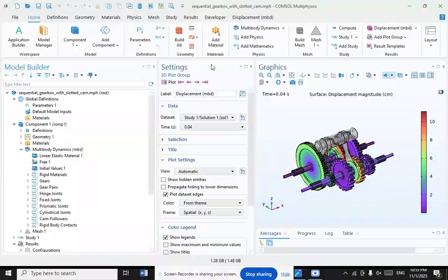The fixed and the free gears can be mounted on either the input or output shaft or both. For example, a 5-speed transmission might have the first to second selectors on the countershaft, but the third to fourth selector and the fifth selector on the main shaft. This means that when the vehicle is stopped and idling in neutral with the clutch engaged and the input shaft spinning, the third, fourth, and fifth gear pairs don't rotate.